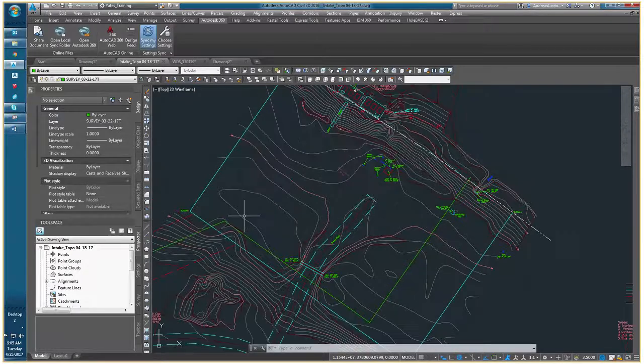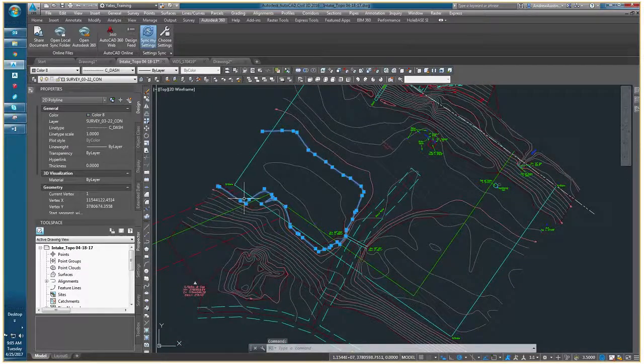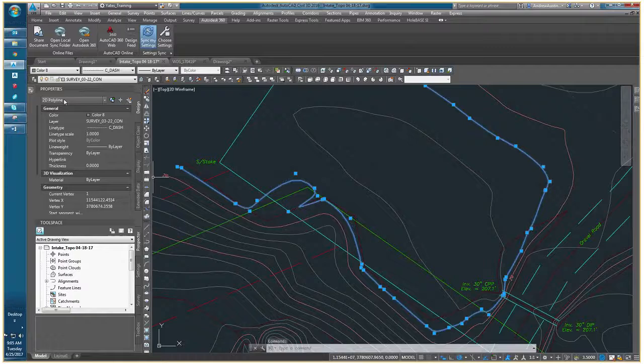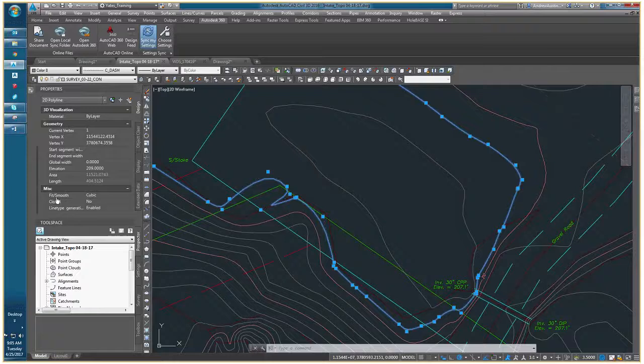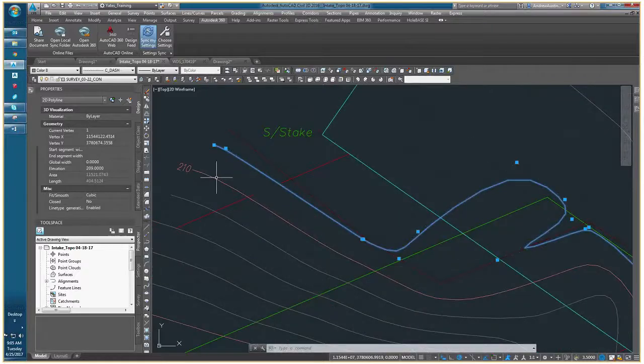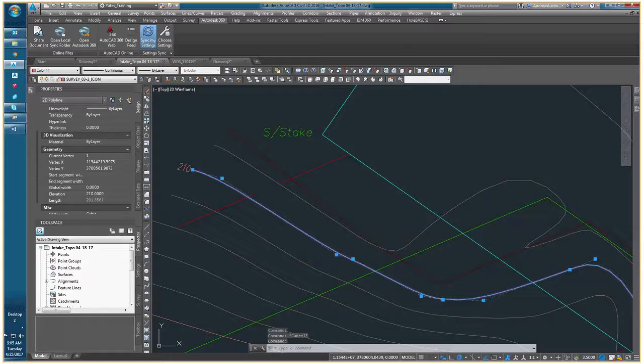The first thing we're going to do here is isolate the contours and then bring them into one of our Civil 3D templates. So I'll first click on one of these to verify that it's a polyline and not some other type of object. Here it's giving us the information that it's a 2D polyline. That's fine. We just want to verify that it's at a proper elevation based on the properties within the elevation property. And I'll check a major contour as well, and check that it's at elevation as well.